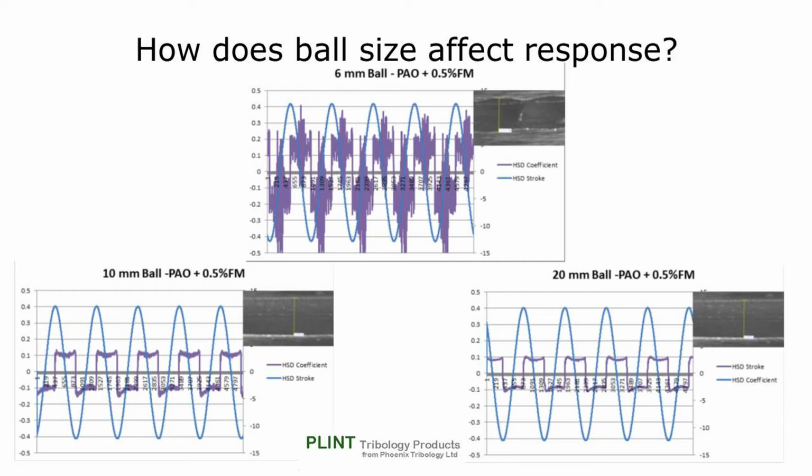In the former, plastic flow occurs on the plate specimen, resulting in a wavy edge wear scar. This results in unsteady instantaneous friction force around the mid-stroke and a correspondingly high value of friction noise.